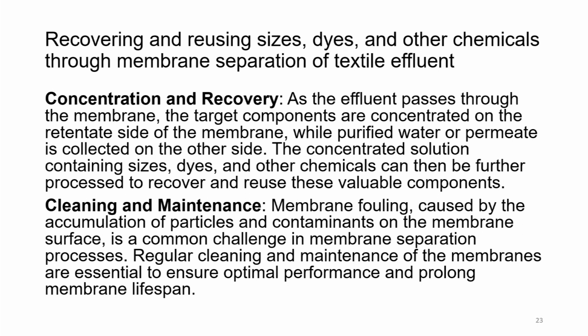Cleaning and maintenance. That is very crucial because membrane fouling is a major problem caused by the accumulation of particles and contaminants on the membrane surface, and it is a common challenge in membrane separation processes, whether it is ultrafiltration membrane or microfiltration membrane or nanofiltration membrane or reverse osmosis.